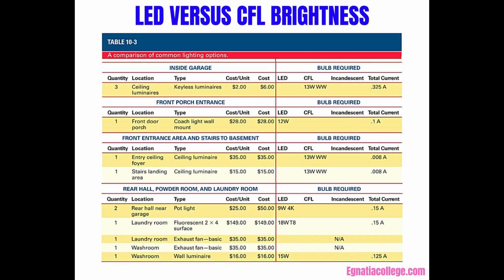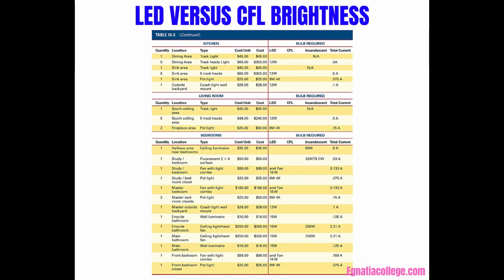Keyless luminaires are standard fixtures that are typical in areas which require light. They are made of plastic or ceramic material and use an A19 bulb. Keyless means that they require a switch to turn them on or off. A pull chain type requires constant power and the switch is the pull chain on the luminaire.